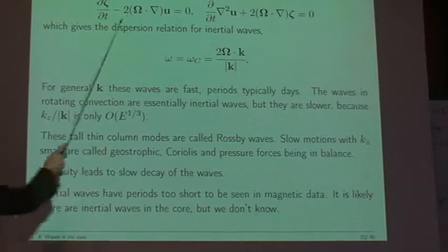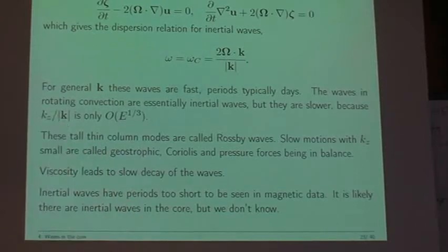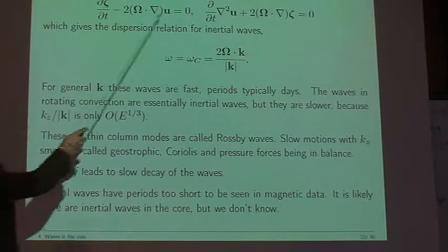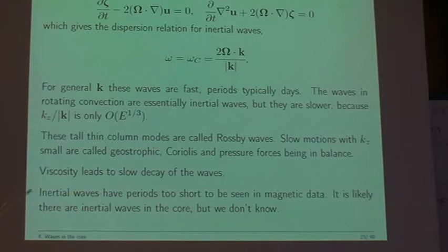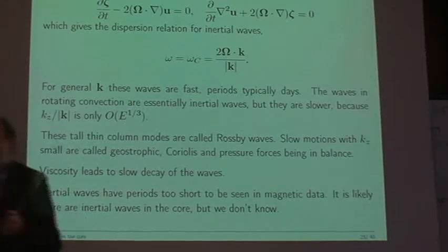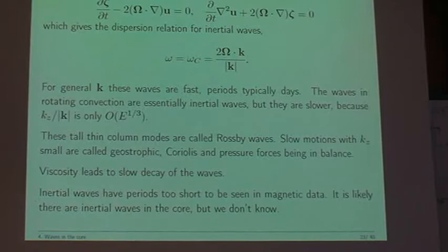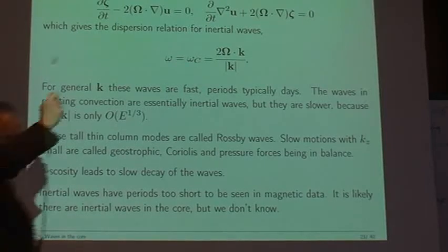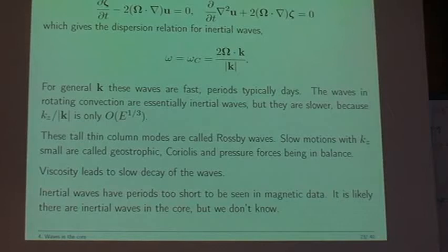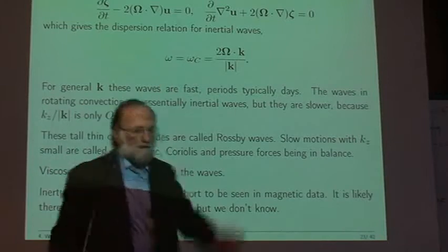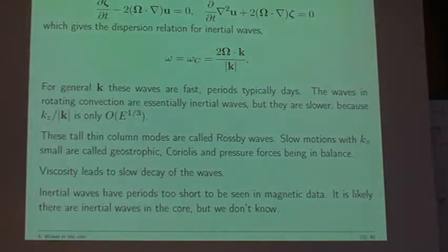Okay. So the first thing you can do is take the curl and double curl as usual, and the z components, and that will give you these two equations. Then you can eliminate, putting the e^{i(k·x − ωt)} formula in there, and you end up with this dispersion relation, which is the dispersion relation for inertial waves. Physically, the way to think of this is that the rotating fluid is permeated by vertical vortex lines. These vortex lines don't like to be bent, so when you bend them like that, they spring back and start wiggling backwards and forwards. They are essentially vortex lines which don't like to be stretched, and therefore vibrate.